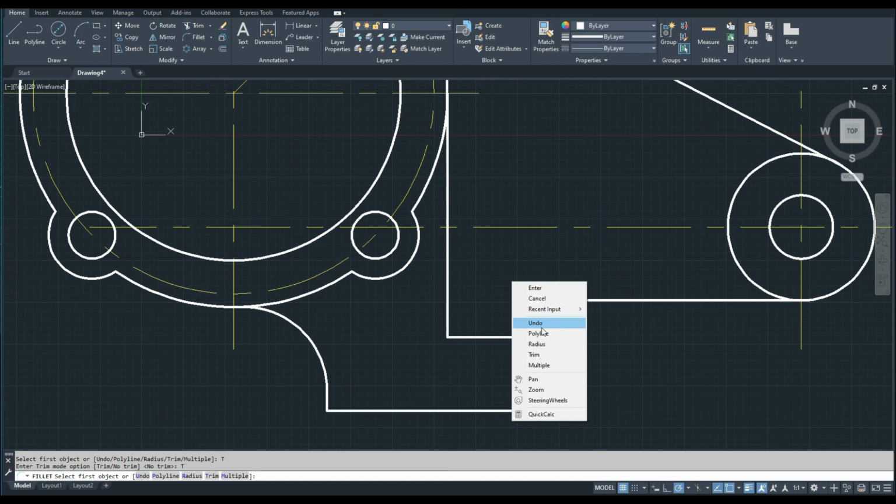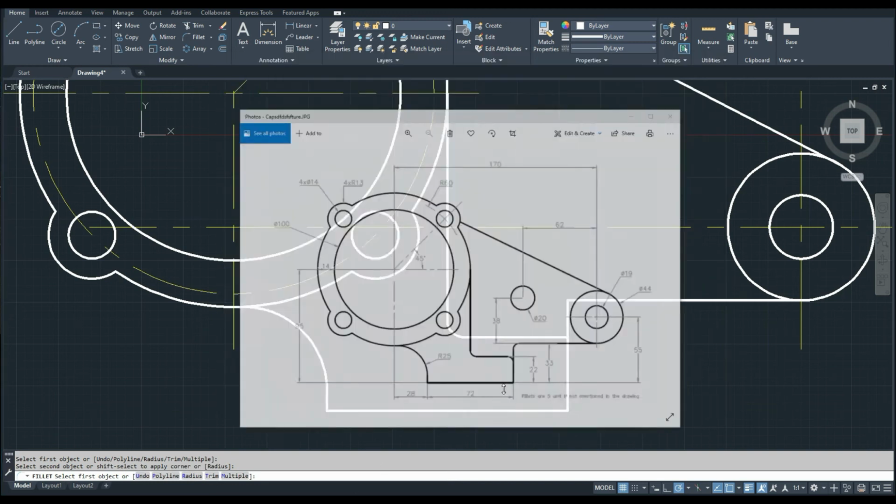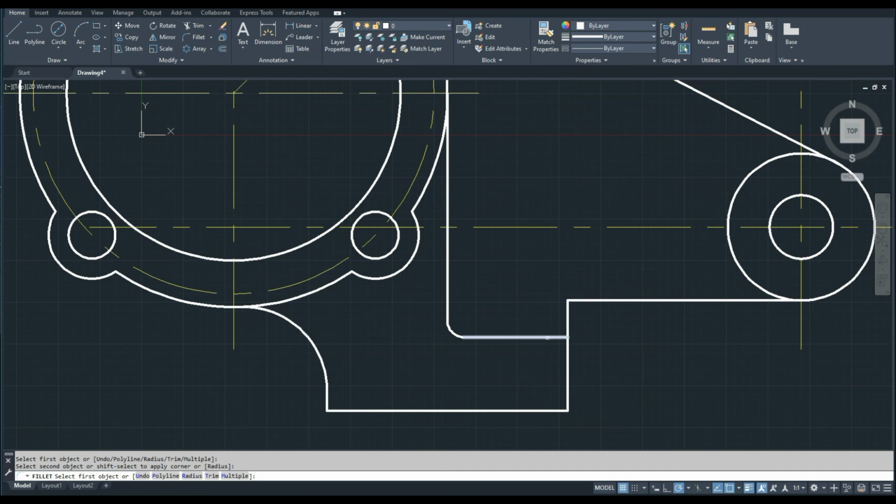We also need more than one, which is multiple fillet. Choose this line and choose this line. This is done, this is the first one, and we have this one. Choose this line and this line, but in this case it will make a trim. I will make extend, never mind. Or we can do the following: click on this line, click on this grip, and move it to here.